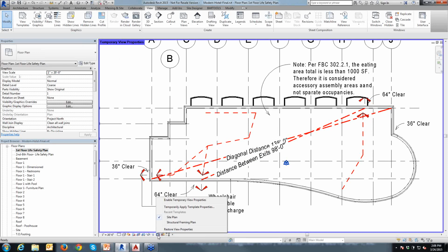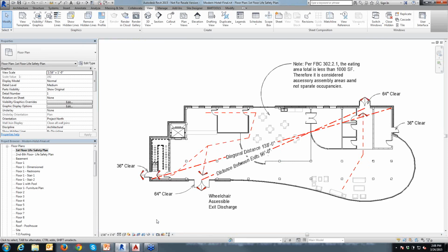Okay, and I think one of the distinctions we need to talk about is the language that Revit uses for all these. So we're talking about, the webinar is covering project templates as a whole, and right now we're talking about view templates. Again, they're using the same word to mean a different thing, but this is just the view properties in here. So if you have some confusion, let us know or pop us a question. We might have to explain a little bit earlier, a little bit better, because I know early on people get lost on this terminology. Yes, so the view templates are used to set things that you would normally do in your visibility graphics that you have to change per view.